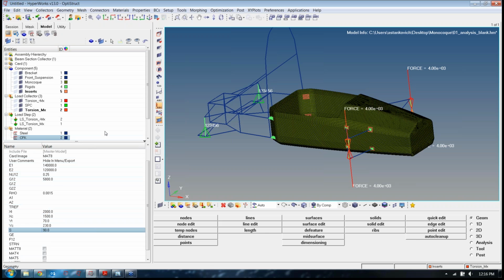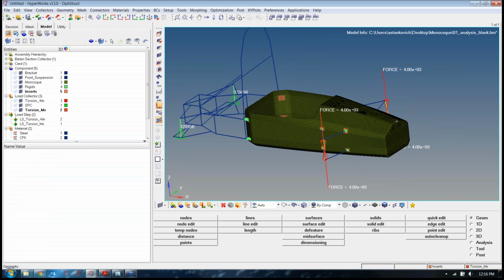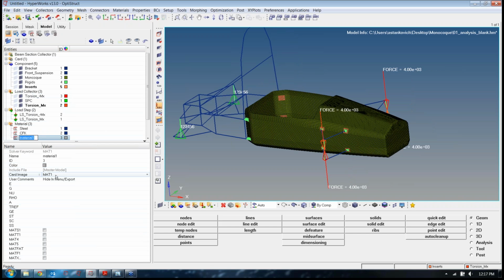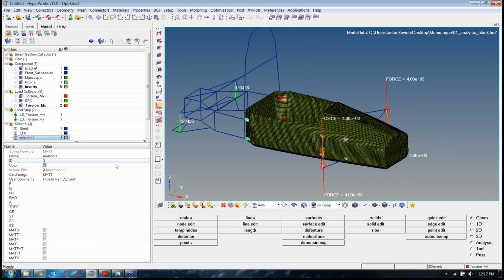So now that we've set up one material model, that's going to be the carbon fiber that we use, we'll also create another material model. This one is going to be for the core. Many times when you're working with composites, you'll have a core of some type of foam or cellular structure, and then you'll have composite layup on top of it. So we'll go ahead and fill these in really quick.